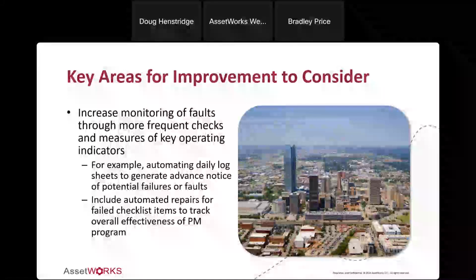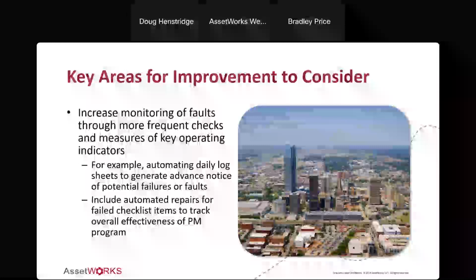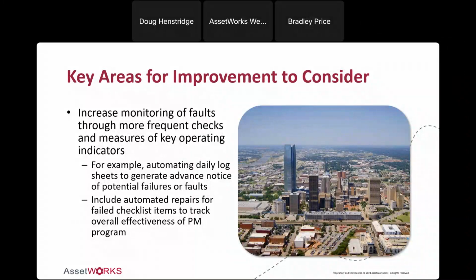So one of the things to do is automating this, where you're basically doing an electronic log that now becomes reportable, and that can even have notifications when it drops above or below certain values, assisting in early warning on things that could be an indication of a pending failure, so that you're not going to repair a failure, but you're getting out in front of something that may be a problem.